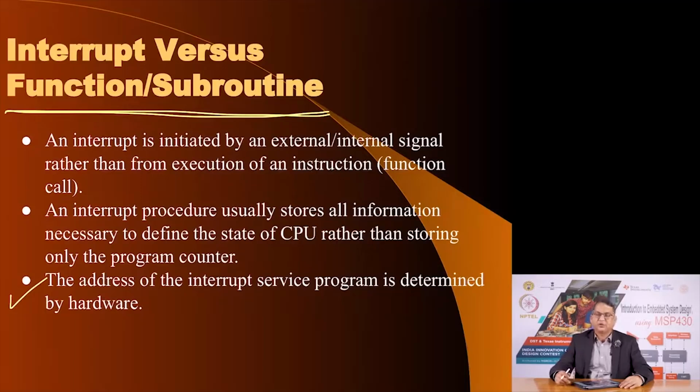The address of the interrupt subroutine is determined by the hardware. The address of a normal subroutine is determined by the software. Depending upon how big your code is, the assembler or compiler will put that subroutine at some place, and that place can change, but the subroutine for an interrupt is decided by the microcontroller, meaning it is decided by the hardware, and when we see the details you will realize what I mean.